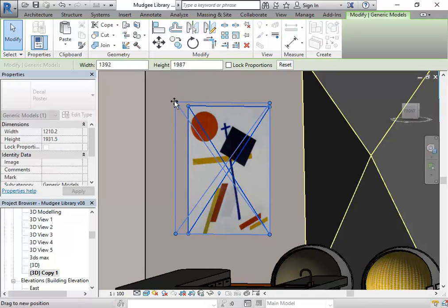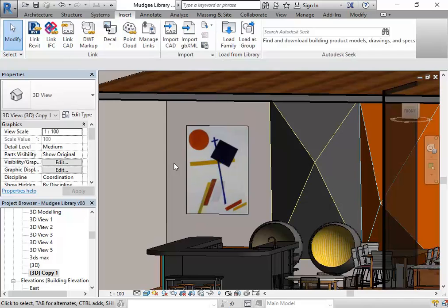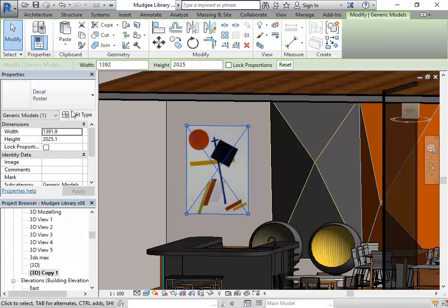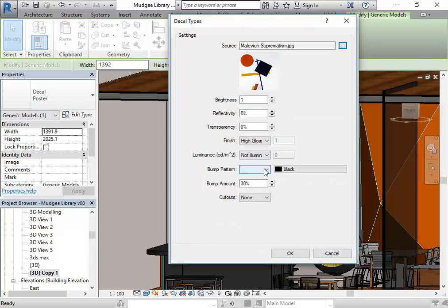Would you put another layer or what? You can, yeah. You can use a mask to do the transparency if you want to. So if you select the image, you'll see when you get to the decal, it's got this option here for cutouts, and then you can choose an image, and that'll put a mask on to cut out parts of it. So that can be really effective.